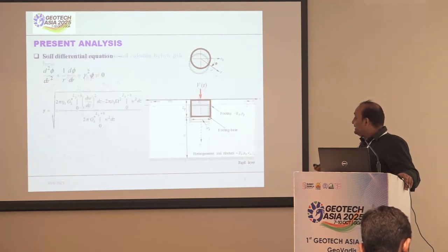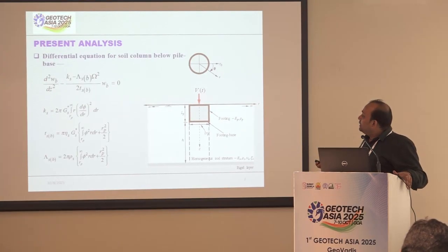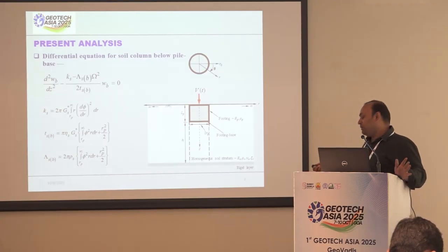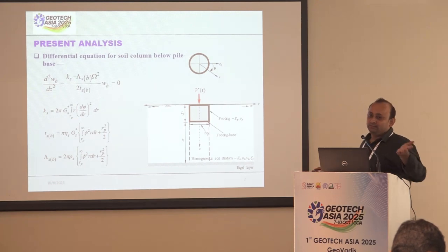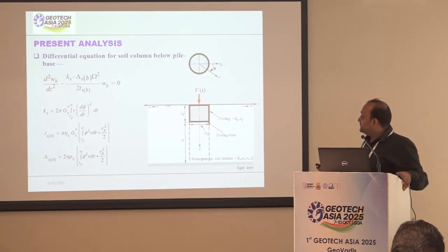Now there is an analytical solution available, or it can be solved analytically. Otherwise, we have to do numerical solutions, which we usually avoid. Then you have a solution for this differential equation as well, for this part of the soil. In this equation, you see that there are parameters Ks, Ts, and omega s, which are soil parameters. Ks is the compressive resistance, Ts is the shear resistance, and omega s is the inertial resistance of the soil. Obviously, Ks and Ts are two associated parameters, so it is better than plane strain, one cone-based model, and other lumped parameter models where parameter fitting is required.